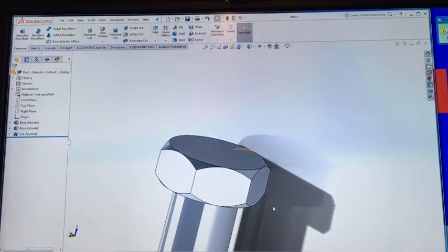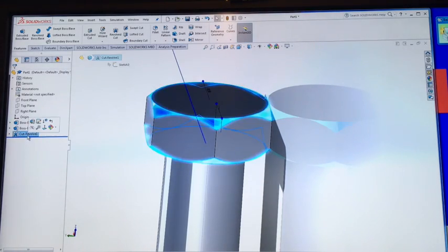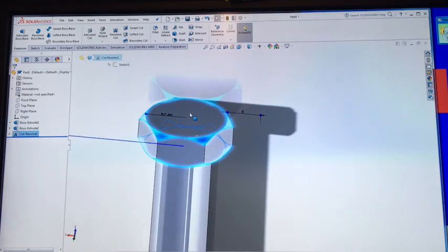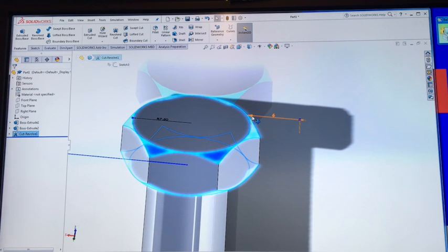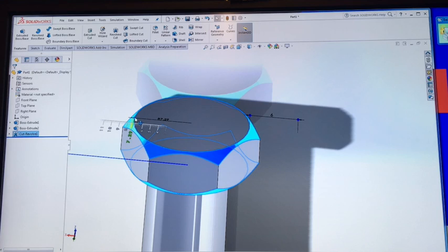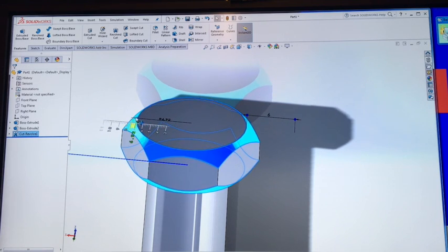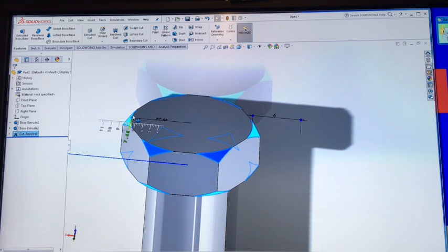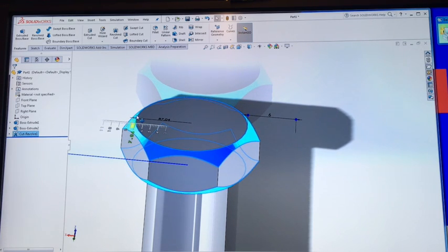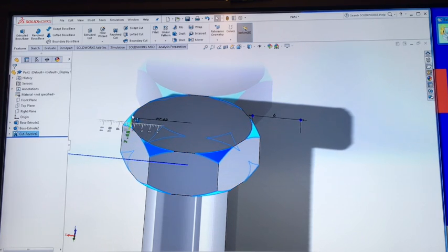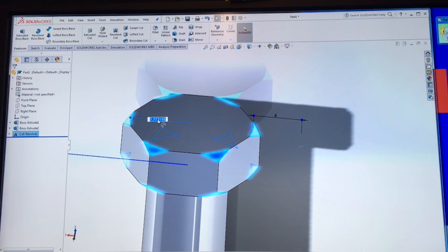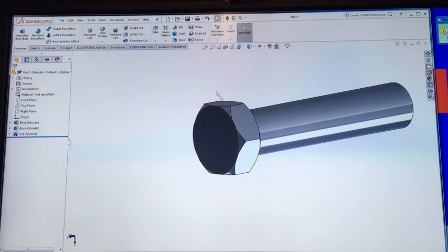Okay. Now if you don't think the size is right, what you can do is click here and drag these numbers around. So I think it's the 7.5 that affects how big or small that cut is. If you wanted it to join all the way around, you could bring it in. If you want it to be separated faces, you drag it out. Round off the number, and there you go, nice little detail around that head.